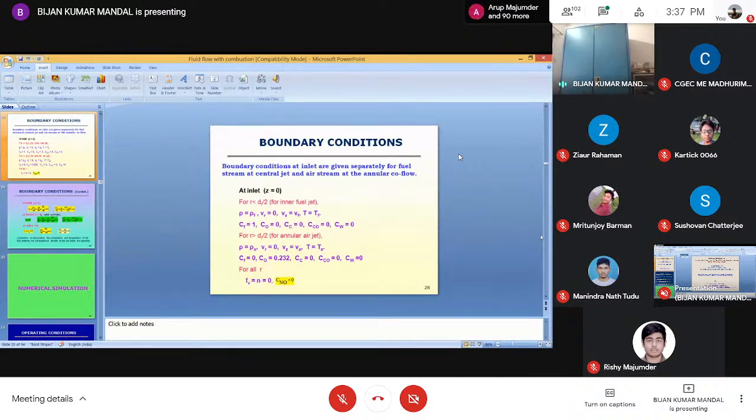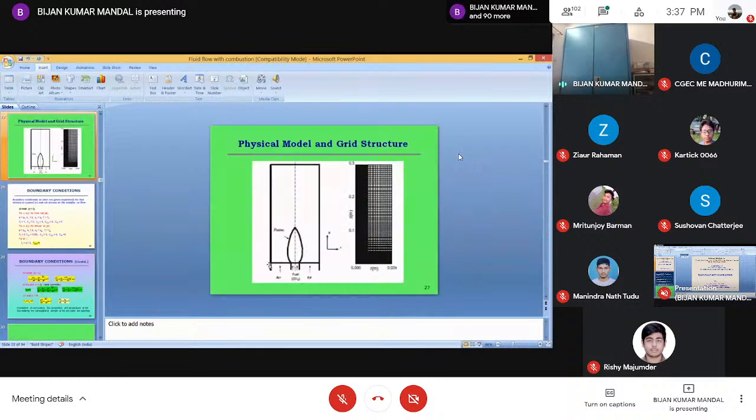So here also, we have to know from our experience what the boundary conditions are. Now you can see the Z direction. If you go back to this, Z equal to 0 is where both of them are entering, and this is Z equal to this length, which we have taken as 30 centimeter, which is good enough so that it becomes steady there.